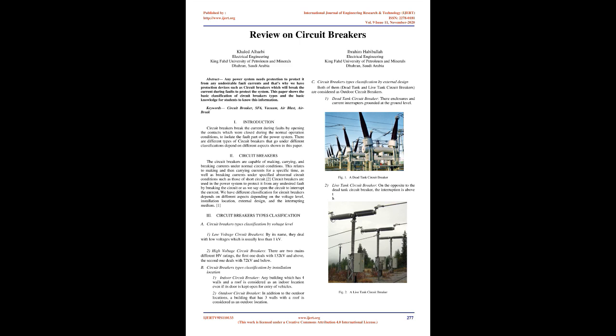1. Indoor circuit breaker. Any building which has four walls and a roof is considered an indoor location, even if its door is kept open for entry of vehicles. 2. Outdoor circuit breaker. In addition to the outdoor locations, a building that has three walls with a roof is considered an outdoor location.